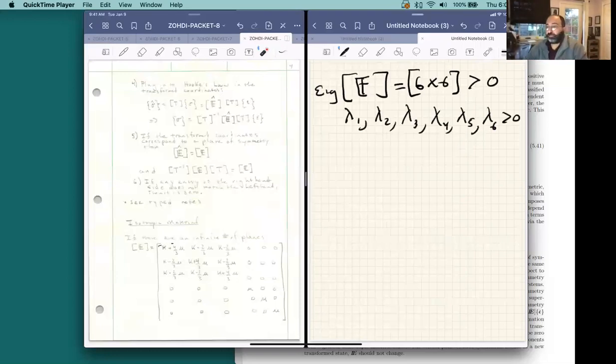So one of the first things that people do whenever they do experimental measurements, and they measure all of these 6 by 6 constants and come up with an elasticity tensor, one easy way to check immediately if the experiments are wrong or that there's been a mistake, is to compute the eigenvalues of whatever they've measured.